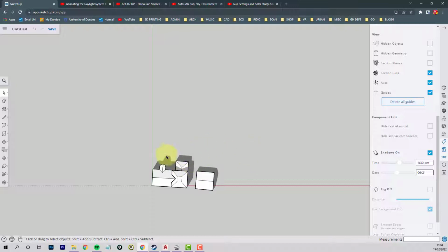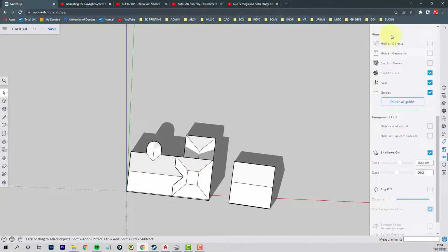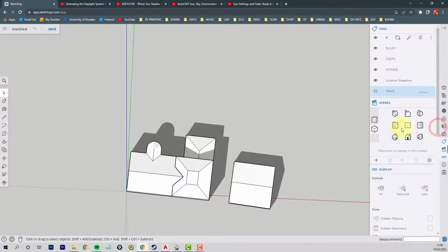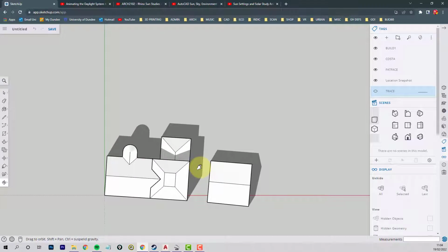Obviously, in the winter, most of your site is going to be compromised by shadows, so really you're looking for a shadow study on the best day of the year initially, so we can get in a bit closer so that things are better to see. So I'll just put that back to plan. I keep forgetting to press shift when I want to pan.